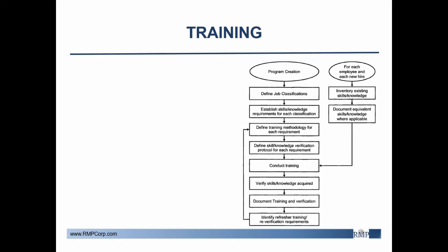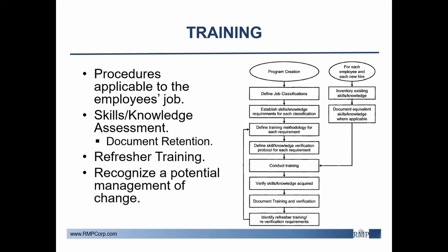We'll cover this more in another webinar, but it must include instruction on how to recognize activities that are not replacement in kind and thus would trigger an MOC, or management of change. The requirement that training be provided as applicable to an employee's job tasks to ensure that they can perform it in a safe manner causes the most confusion from what we've seen. The broad regulatory statement infers the following. 1, that requirements for the process overview, potential hazards, job tasks, and how to recognize a change that would prompt an MOC. 2, training in the safe practices that maintenance technicians are required to perform their work.